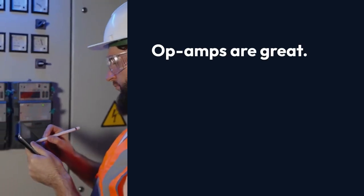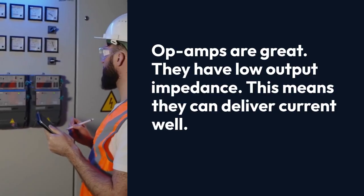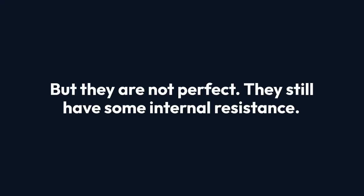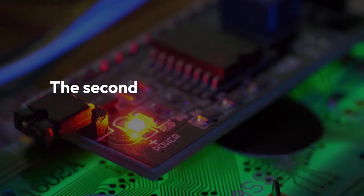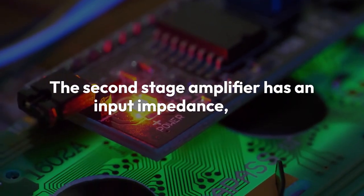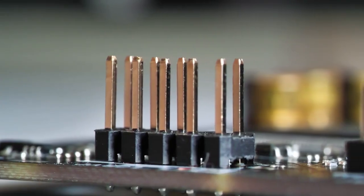Op-amps are great. They have low output impedance. This means they can deliver current well. But they are not perfect. They still have some internal resistance. This is the output impedance, Z_out. The second stage amplifier has an input impedance, Z_in. When you connect them, these impedances interact.